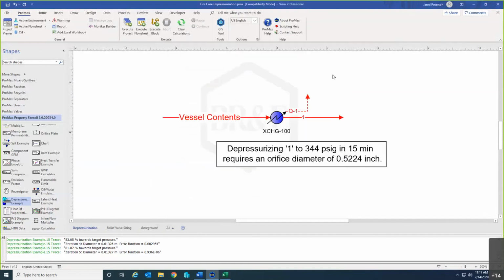So with that said, that was what I had planned to cover for this webinar. We've gone over adiabatic, what's happening under the hood with this depressurization. The depressurization tool is doing more or less what we did by hand. It's just doing it far faster, more efficiently, and more powerfully. It does have some limitations. If I had mass coming in, or if my volume was changing, this does not allow that to happen. But I could still set that up and do that without too much effort, as you saw.